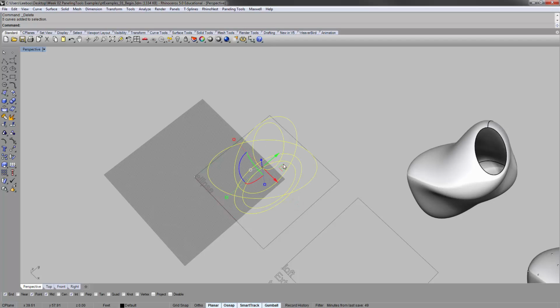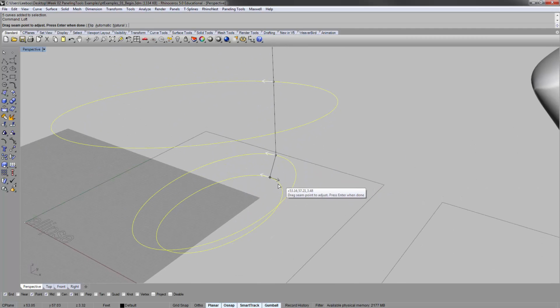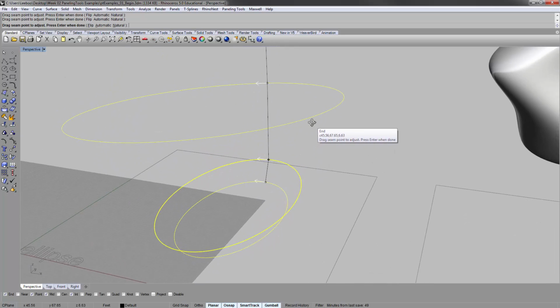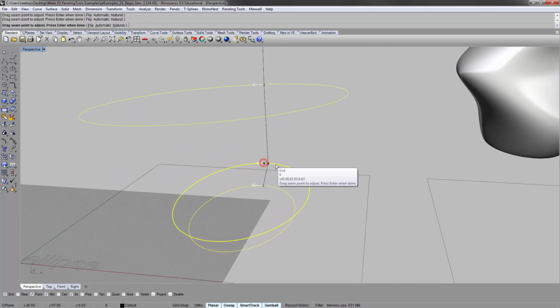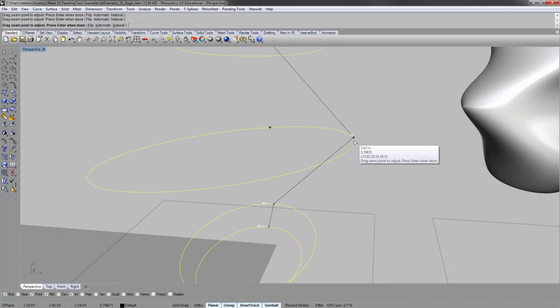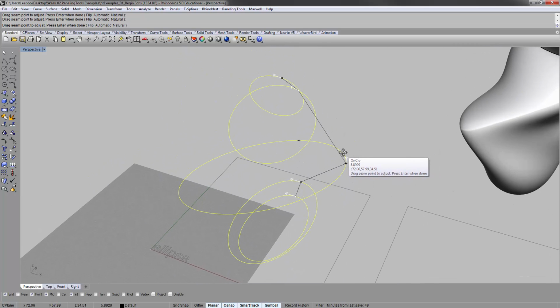So when you're lofting this, you have to make sure that you adjust these seam points. Now the seam points should be at the end of the ellipse by default, right? So if I move it around, it should snap to the end. What you need to do is go around these step by step, and drag these so they are snapping to an end point, just like mine. So I'm dragging it to the end point and looking for it. And yeah, there.